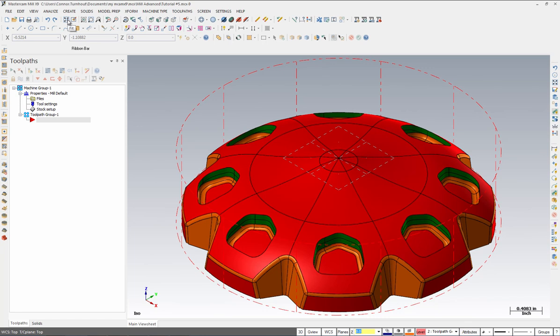For the first toolpath, we're going to rough out the part using Surface High Speed Area Rough. The Surface High Speed Area Rough toolpath is designed to machine standing bosses and cores, cavities and pockets, or material that other toolpaths left behind. From the status bar, we're going to make sure that we change our main color or wireframe to a dark blue.